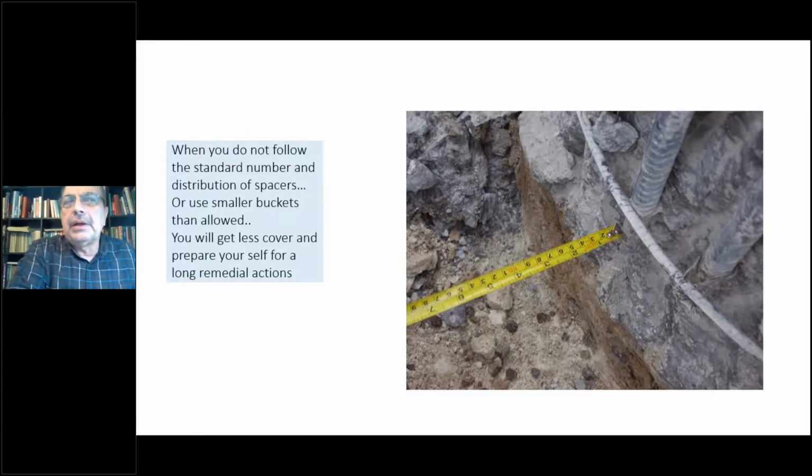Sometimes contractors also use smaller buckets, because they don't want to bring the exact diameter of the bucket, so that they will not pour additional concrete and lose some concrete. You must use the exact dimensions of the buckets in excavating the borehole of the pile. Of course, if you have a smaller cover than the design, you will get a lot of cost in repairs and delay damages for these piles. You may sometimes need grouting. You may sometimes need to excavate around the pile, expose some part of the pile that is very important for the structural loading, and add cover to it.